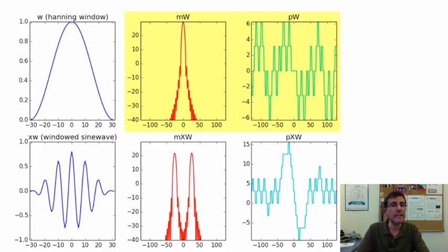And now if we take the DFT of the windowed sinusoid, what we are seeing is basically the same shape as the window, but at the frequency of the sinusoid, the two frequencies of the sinusoid, the positive and the negative frequencies, and at the phase of the sinusoid too. So we have the two values for the two phases with this anti-symmetry that this analysis results in.